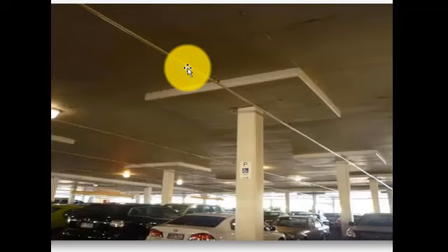There are no beams here too. This is the rib. It is the rib, not the beam. But even though it is a rib, it is still performing the same function as a beam. Do you understand? So we can't say a waffle slab or a rib slab does not have a beam. Of course, this is working as a beam. But for this flat slab, there's no beam at all. So this is a flat slab.